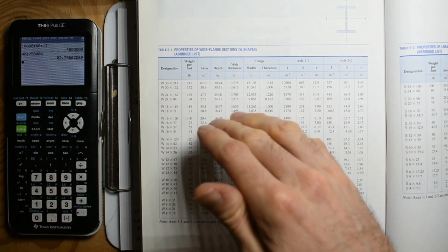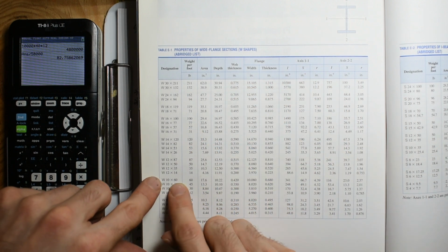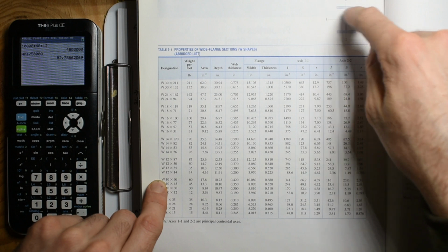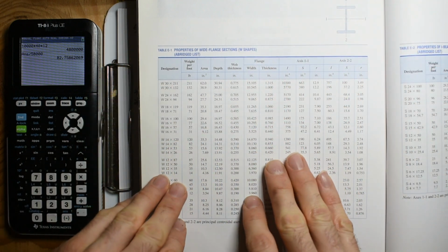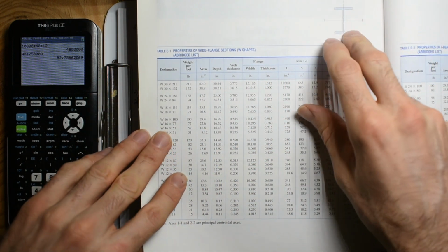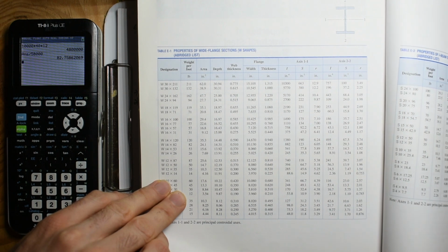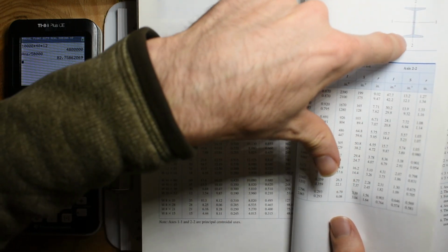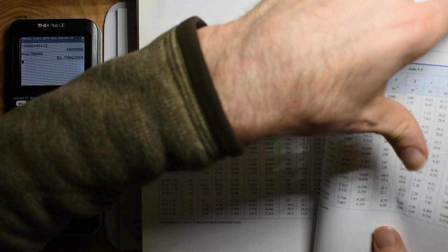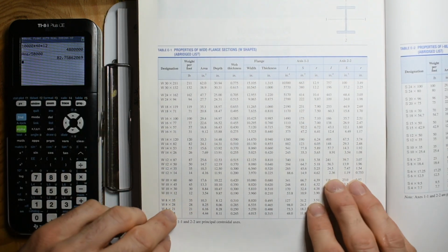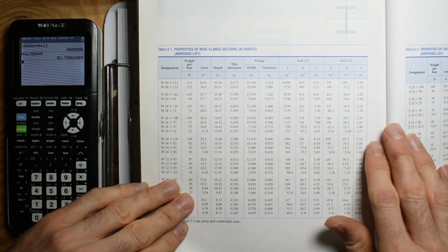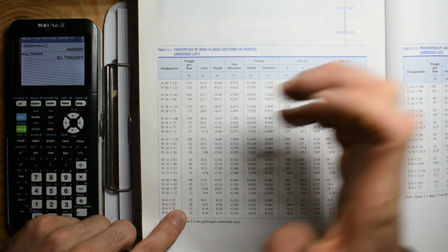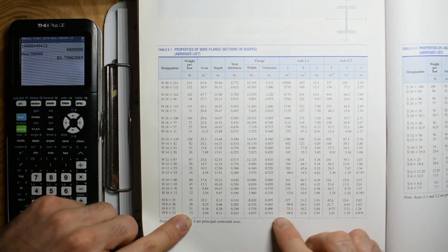The 10 is the height of the beam, just nominal. And then it's a W. W doesn't mean weight. It just means that it's a W. It's a wide flange beam. I'd call them I-beams, but people call them wide flange beams. I-beams are narrow, and the true I and their S, they're definitely more curvy on the inside. Anyway. More for vertical loads. These can be loaded in 4 directions.